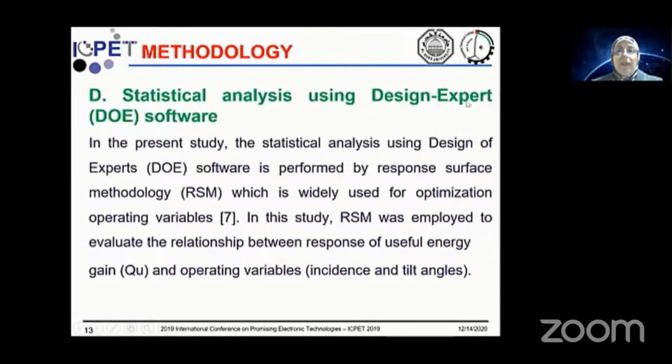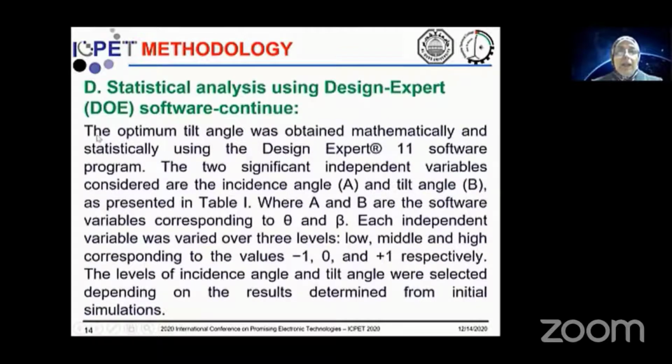Statistical analysis using Design Expert software. In the present study, statistical analysis using Design Expert software is performed by response surface methodology, which is widely used for optimization of operating variables. In this study, RSM was employed to evaluate the relationship between the response of useful energy gain and operating variables like incidence and tilt angles. The optimum tilt angle was obtained mathematically and statistically using the Design Expert 11 software program.